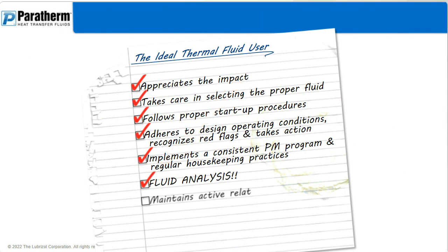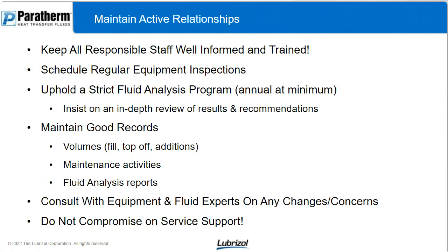Finally, an ideal fluid user will maintain active relationships with all key stakeholders. They'll keep all of their staff well informed and trained. Communicate on-site. Okay? Stakeholders aren't just outside, they're internal as well. Schedule regular equipment inspections with your equipment manufacturers. Have them review what's going on. Follow their PM programs. Uphold that strict fluid analysis program, annual at a minimum, and insist on an in-depth review of the results and recommendations.